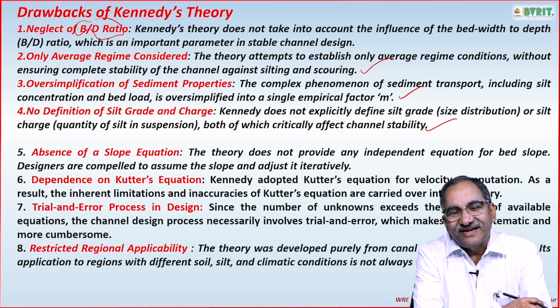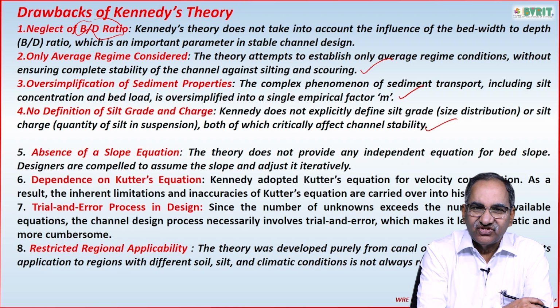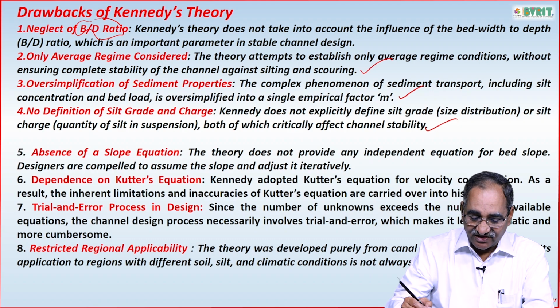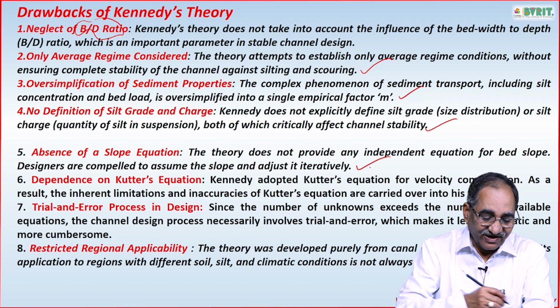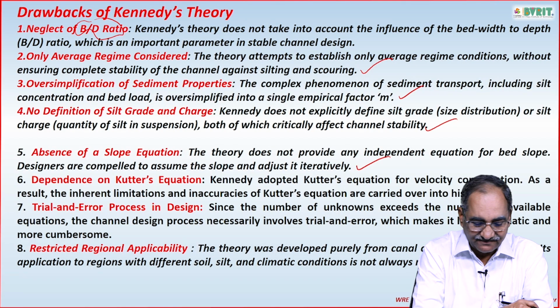Next, he never explained any slope equation, because most of his theory takes the critical velocity straight away, and from that only he has taken the whole thing. So no slope equation is given, whereas the longitudinal slope is a very, very important parameter in channel design.